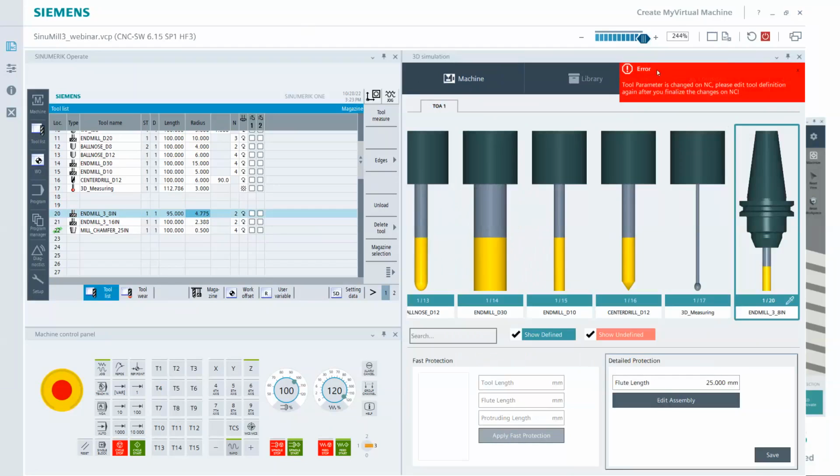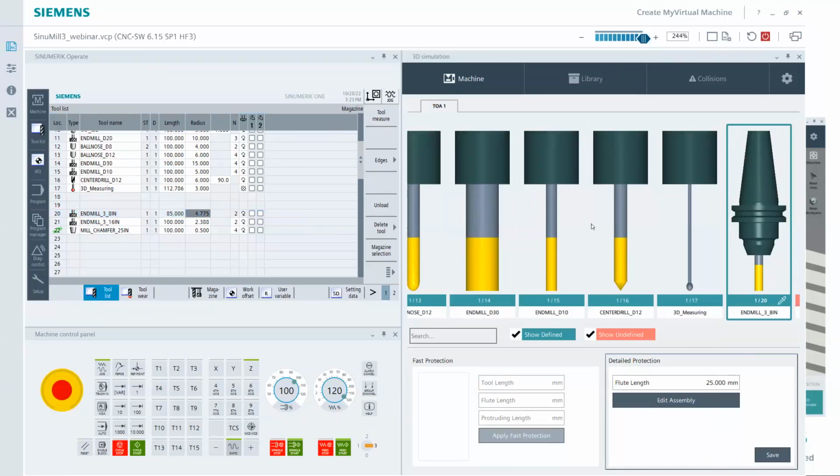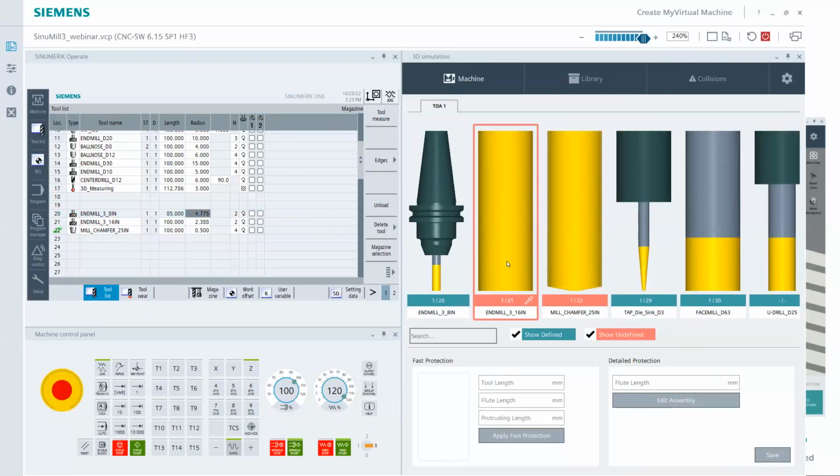See how it gave me an alarm and it never actually took. So be careful of that. You want to make sure you've saved it before you make any changes to the tool projection, or it may or may not take. So it's really that simple. I mean, there's not a whole lot when it starts to defining and bringing these holders in, as long as I have that 0, right?